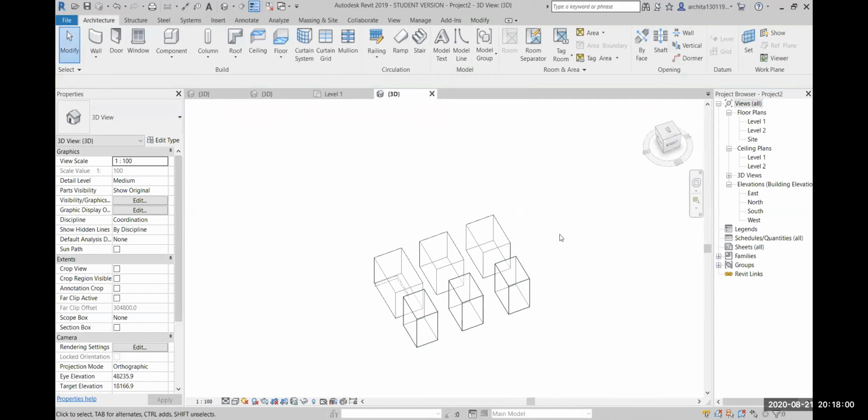Okay, it is showing two options: override the existing version or override with the parameters. Because I think you made the changes in the one conceptual mass which you already loaded into the project. You have made the changes in that conceptual mass file only, and then you're trying to load it again. That's why it's asking whether you want to override the parameter changes you have done or not. So click on the second option, override with the parameters. Click on the second one.